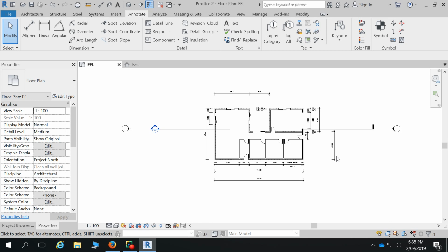Any questions about some of those things we've done? If you change a door to a window, or vice versa, will it change then the icon tab? Like on here I had oval shaped ones. Yep, and windows are like a hexagon. Yeah. So it does. Yep. You might have to re-tag it though, like do a tag. Yeah. Because if you delete it, the tag will go, and then when you place it in, if you didn't have the tag on, you might have to just re-tag it, but it would put door and window tags, because that's associated with the family, what it does.